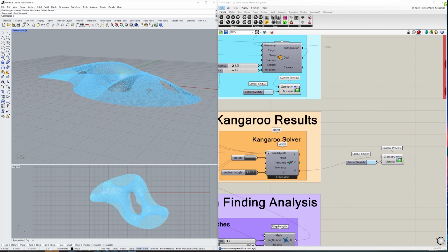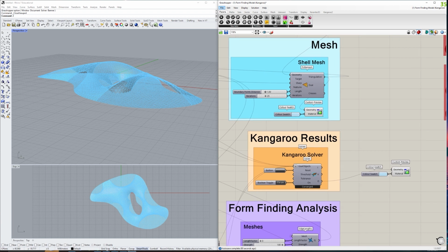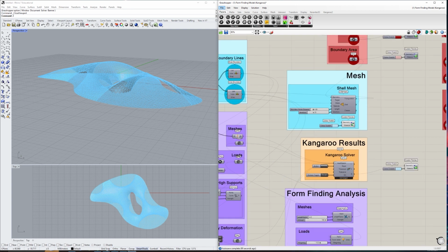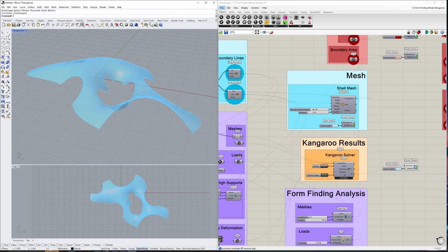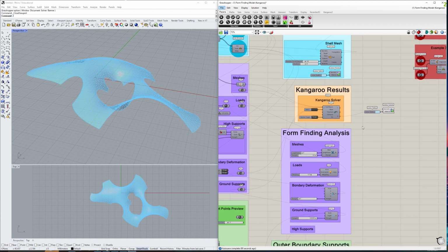On the other hand, there are some notable drawbacks to this script. The boundary correction method isn't structurally optimized and will negatively affect how optimized the structure is. The script is designed for holes in the boundary and breaks when there is no hole. And not that this is significant since the approach here is to adjust the form based on desired support locations, but there's no additional option to automatically optimize support placement positions for a given boundary.